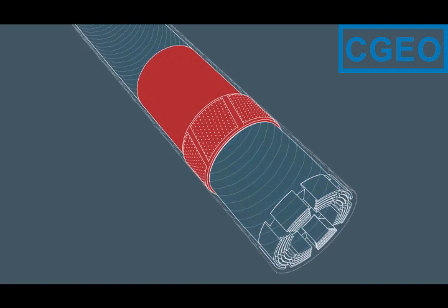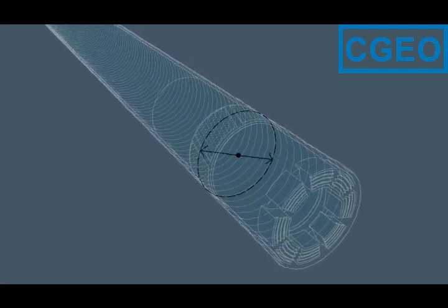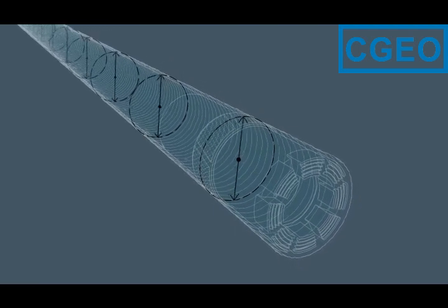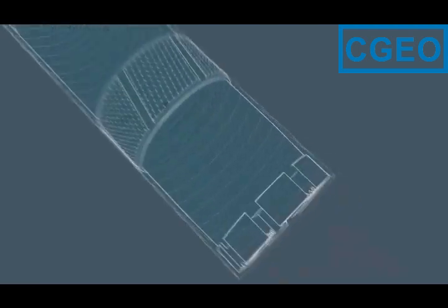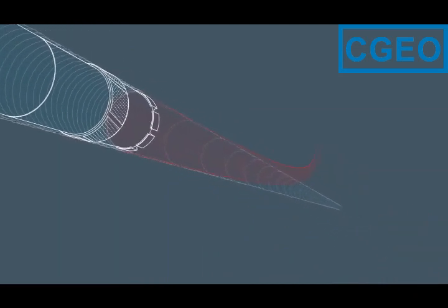The reaming shell has 2 functions. It reams the hole to its nominal diameter, preventing a new drill bit from getting stuck in a slightly conical hole. It stabilizes the core barrel and mitigates deviation of the bore hole.